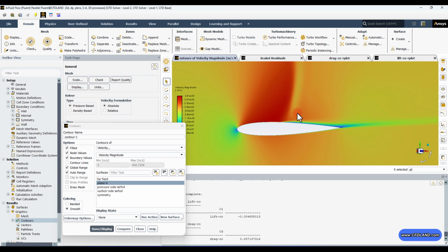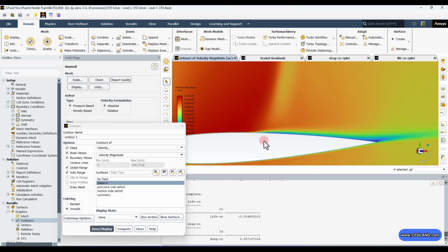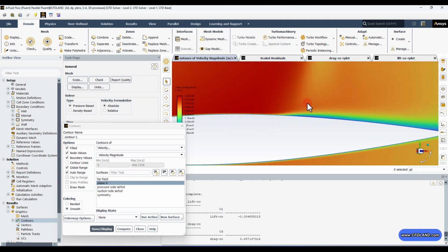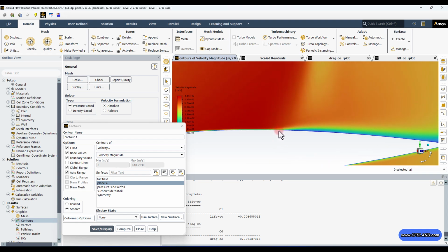You can proceed with this model with LES in order to have the large eddy simulation and see the large wakes forming behind and on the upper surface of our airfoil. But for now, regarding this one equation simulation, we can be satisfied by these results. But what is more interesting in here is that the boundary layer is starting to grow in here, confronting an adverse pressure gradient that causes flow separation at a point somewhere around here.